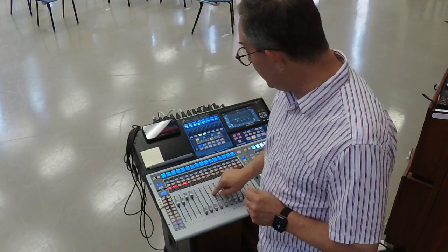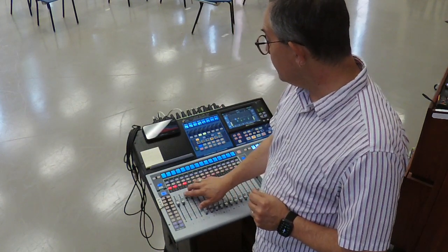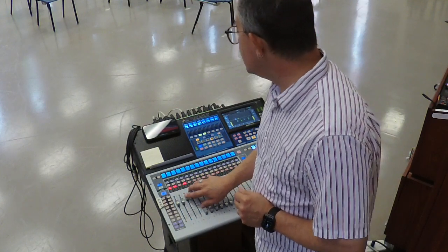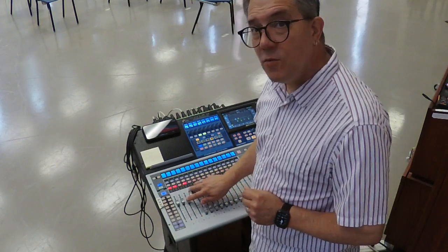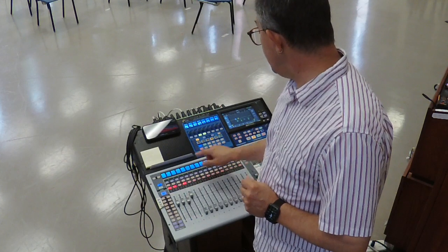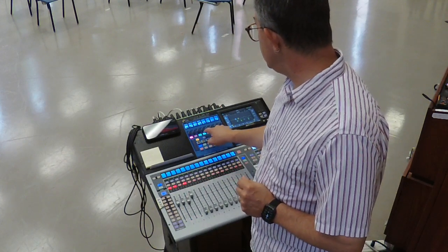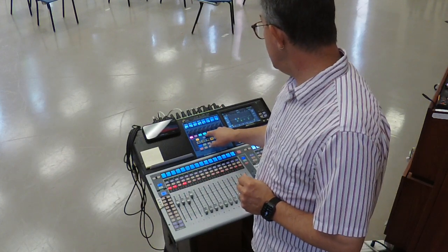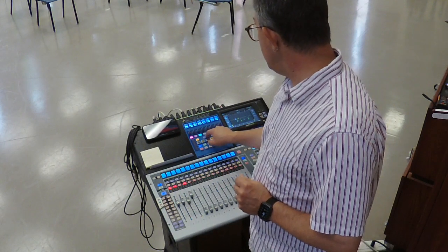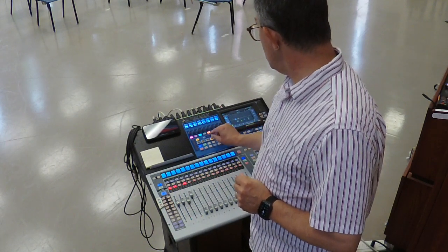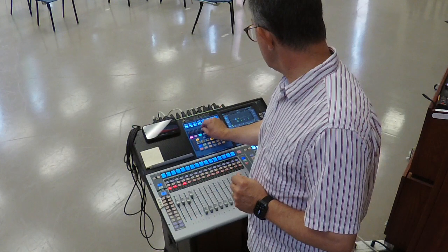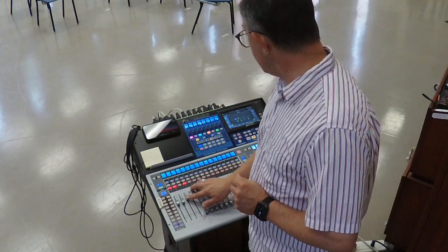Let's go to my third one. I'm going to do exactly the same thing. Create feedback, 147 hertz. So let's go find my channel that's at 147 hertz, which I have lazily set up ahead of time. Turn that down some more. Let's see where else we're getting some feedback.